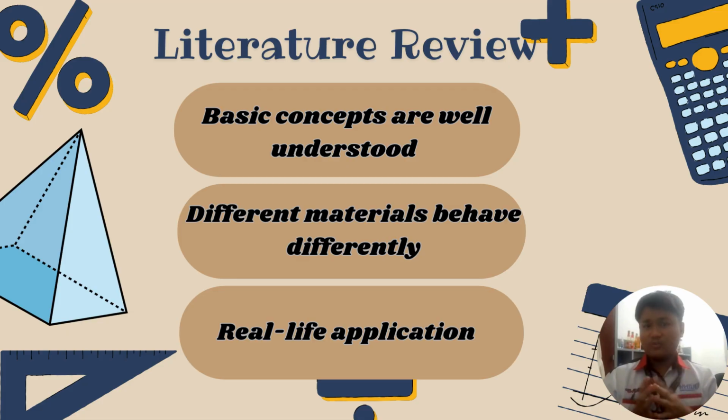What is the meaning of Hooke's law? It's used to calculate exactly how much the member stretches. In Hooke's law, we usually use the formula delta L equal to P times L over A times E, where E represents the material stiffness, A is the area, P is the force, and L is the length.